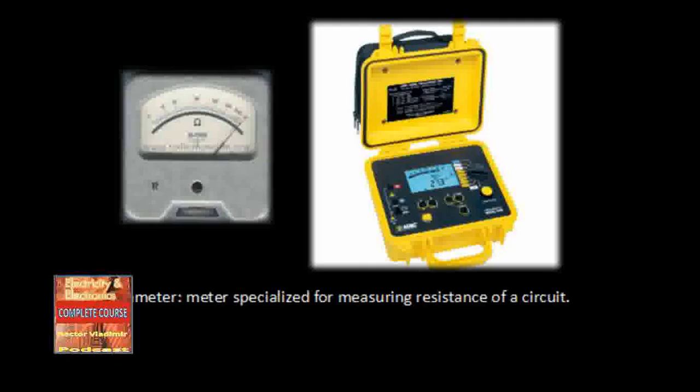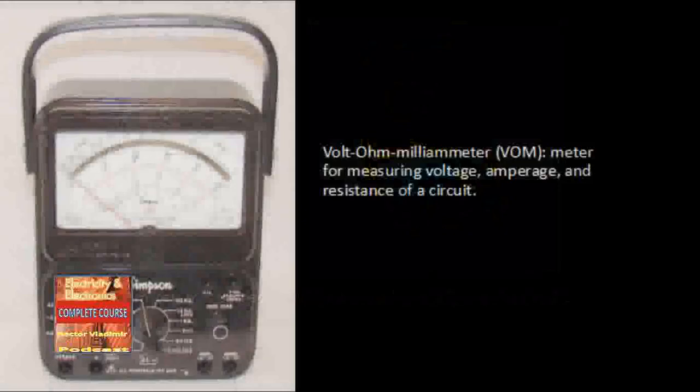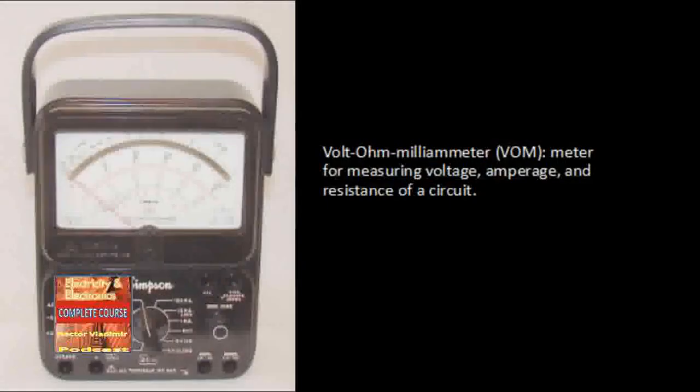near it. To use the ohm meter, first short the test leads together. This applies 0 ohms across the meter. Adjust the ohms adjustment knob until the needle points at 0. The needle should deflect from its position at rest on the left to the 0 resistance indication on the right side of the scale. If the needle does not deflect, it is possible that the battery is dead or extremely weak. After the ohm meter has been calibrated to read 0 ohms when the leads are shorted, you can make a reading of an unknown resistance by placing the unknown resistance between the test leads.